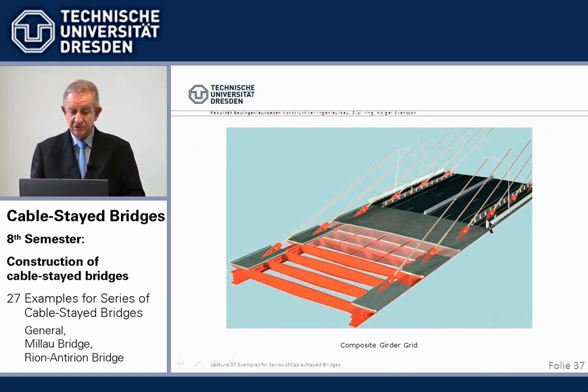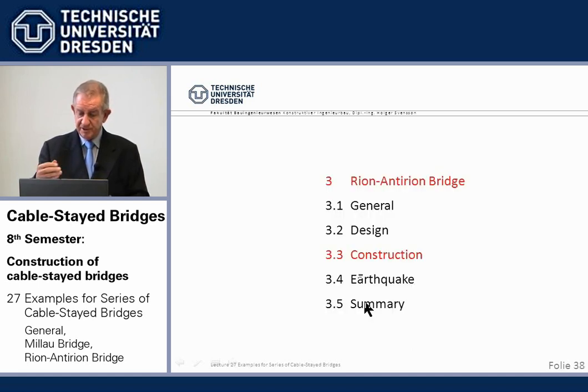The beam, again, you have seen that quite often with my lectures. That's the type of composite beam I prefer. We have a steel grid with open cross sections, keep it simple, and then we have a concrete deck on top, either precast or cast in place. They have a little trick here, I'll show you later. It's cast in place, but before lifting already. So that's typical. We have web extensions, which I showed you were first used for the Hooghly River Bridge and then for Enesys, which takes the forces directly into the webs. All very good and thought out.